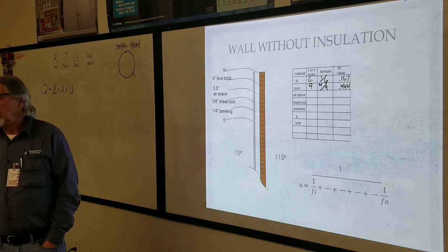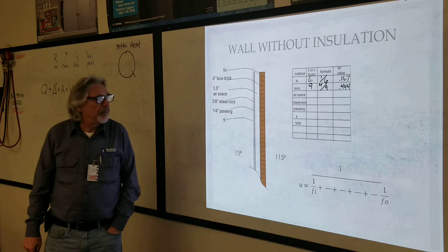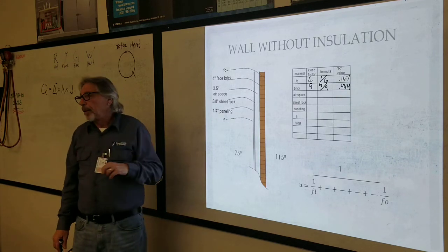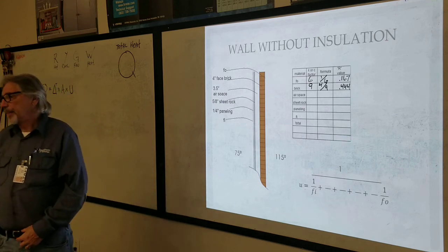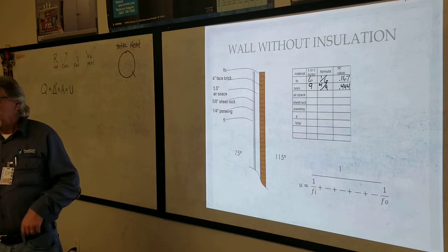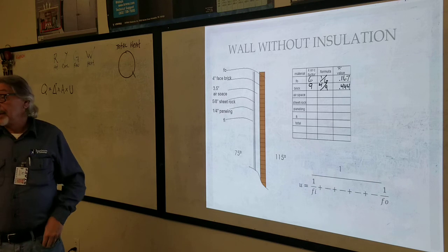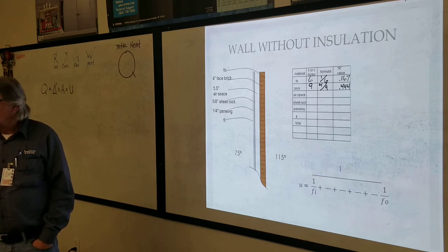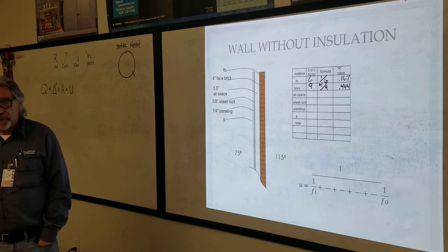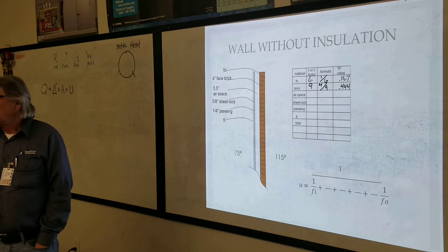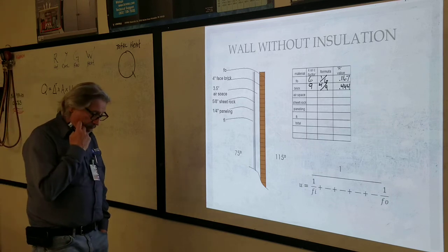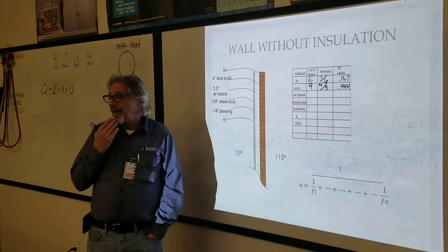Airspace in walls also conduct heat by all 3 heat transfer methods. Let A be the thermal conductance of the airspace in figure 8-4. With the thickness of airspace being considered, if the airspace is 3/4 inch thick or more within a structure, the value of A would be taken as 1.1 BTU if there is no reflective insulation in the airspace.